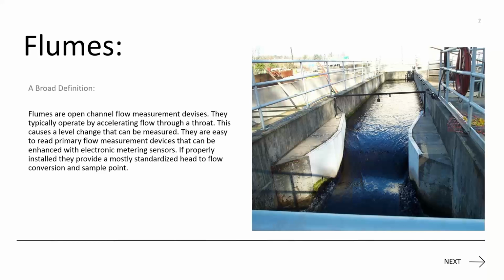They're paired really well with a lot of different electronic sensors that can report that data back to a central unit. So whether it's an ultrasonic meter or a bubble tube or a radar, they all provide a good standardized head-to-flow conversion point and a good sample point to take other draws from.